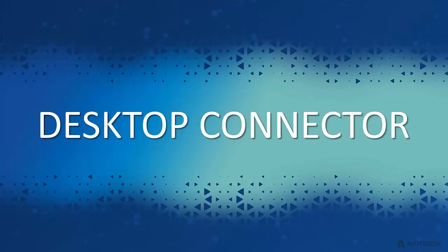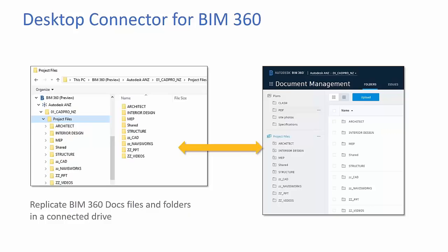Another really powerful tool here that's been inside of BIM 360 team with C4R is Desktop Connector. This works with the BIM 360 design collaboration module. So Desktop Connector allows you to replicate the files from your folder Explorer here and connect it into the BIM 360 document management module. So what we have is you can install this.